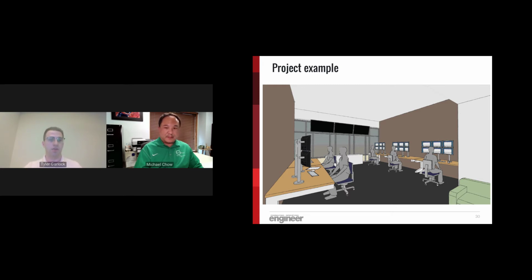So then it became, what were our options in terms of lighting? It was very clear to us that downlights probably were not the best option already, because they're going to be above the people's heads. They don't have good side-to-side throw. So you're going to get scallops on the walls, creating a cave-like effect. So it's not going to be very comfortable for the people working in there.